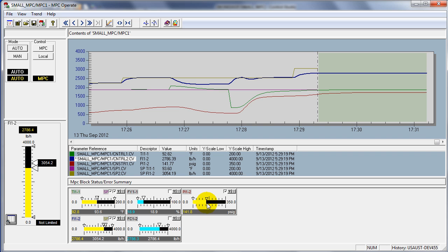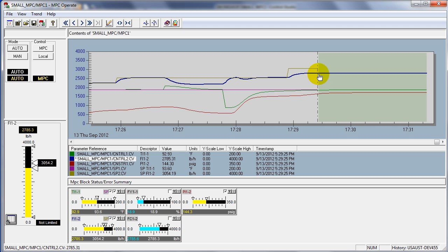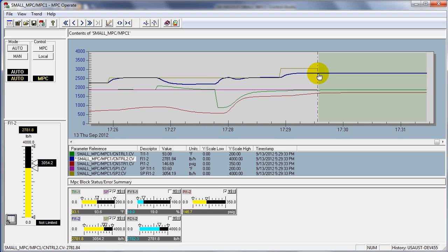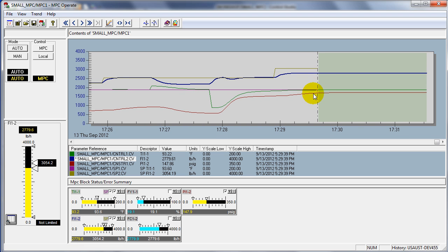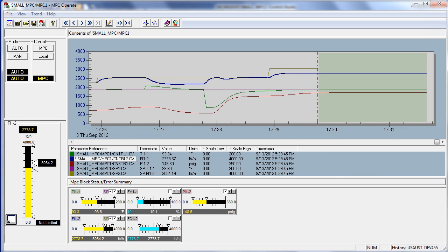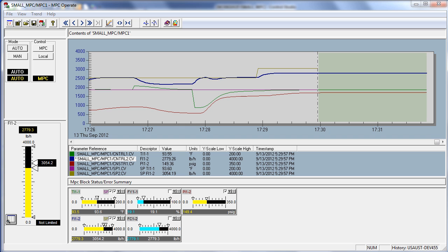So we're maximizing the throughput of our unit within the capacity set by these operating constraints, the pressure of the unit. We're getting the most through without violating our pressure constraint. Now, oftentimes an operator is really reluctant to be operating a unit at the operating constraint, because if anything happens that disturbs the process, then that could cause a constraint violation. In this particular case, where we're operating at the pressure constraint, we'll introduce another disturbance in our cooling capacity to reduce the cooling capacity.